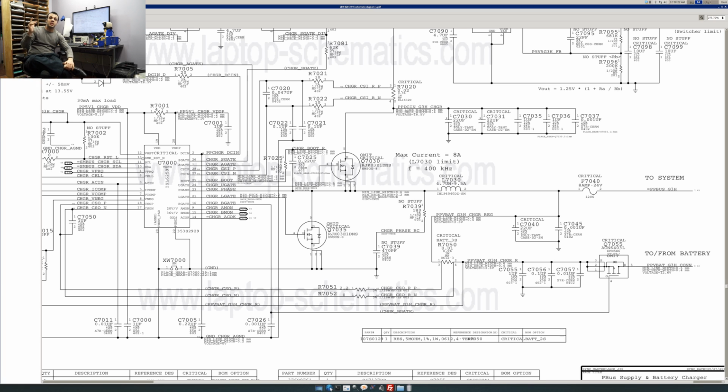So U7000, again, this chip, since it's not actually inside the circuit, U7000 is controlling transistors that create the 12 volt rail for the machine. But U7000 is not actually inside that 12 volt rail. It's not going to know what's happening. But what it does is measure the voltage drop across a constant in the circuit, which is that resistor.